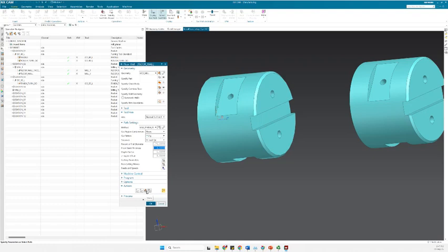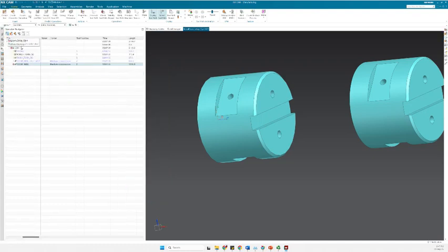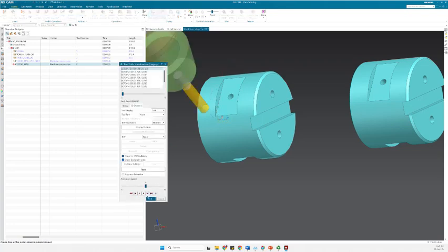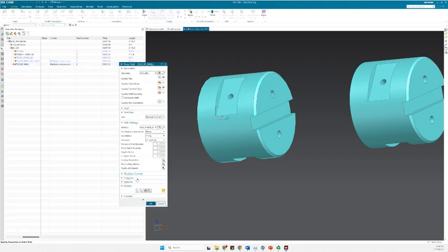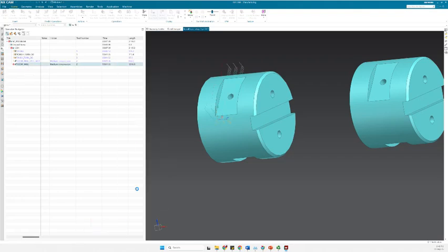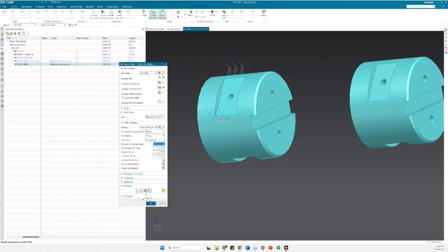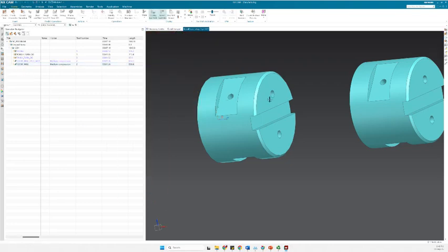All right, let's consider that this is okay and we are done with this process. We can again see that this is now added here, but I have a sign here that maybe it's because I changed the value and didn't regenerate it again. I changed the step over value back to 75, and now it looks okay. So now we have defined this floor wall for this slot.